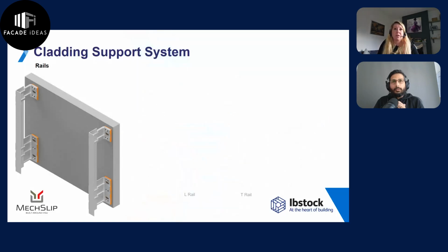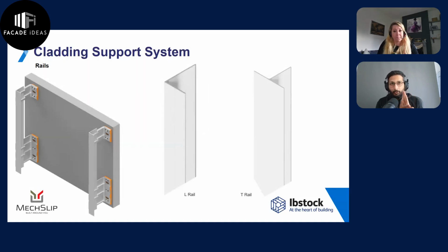It does. And one thing in this system: we talked about brackets, double brackets, single brackets, like you can see on the screen, and the vertical rail. Each rail would have at least one double bracket, which would be the fixed point, and then all the rest single brackets could be divided between that span. That span calculation and all those things would be specific to the project, just like Ray said, and that would come from the bracket team or the supplier, or you could do your in-house calculations and verify with the supplier as well. So work as a collaboration when you're designing these kinds of systems.